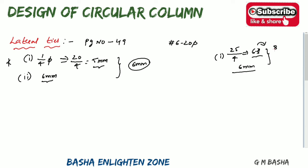So the next best value is 8 mm. Mild steel is available from 6 mm and HYSD from 8 mm, so go to the next best option, which is 8 mm. In this condition you can prefer a minimum 8 mm dia bar as the lateral tie. But here the first condition is 5 mm and the second is 6 mm, so we prefer not less than 6 mm. If it is higher than 6 mm, provide the next best value which is not less than that value.